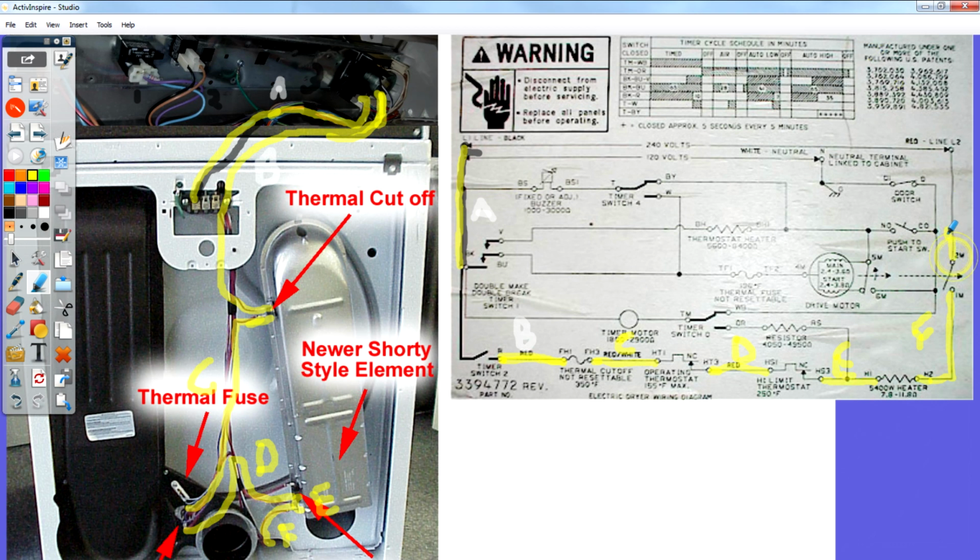Then what do we do here? Back up to that power cord. Okay, I'm going to use a different color. Where on this power cord would I go to? The right side. The far right screw. That would be line 2. So there'd be another wire coming up, and I'm using just the red wire. It would run up here and would connect to that. Now that's a spaghetti mess, isn't it?